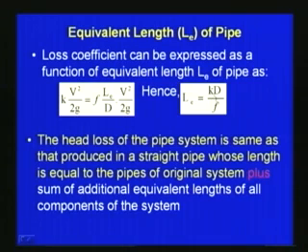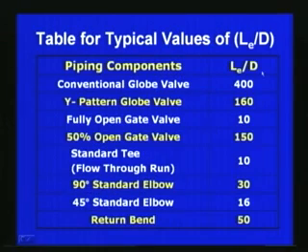So, for the given pipe fitting, K will be constant and known, and the friction factor will also be known, so that we can have this kind of table, and directly from the table we can get this. Once the diameter is known, we can get the equivalent length.